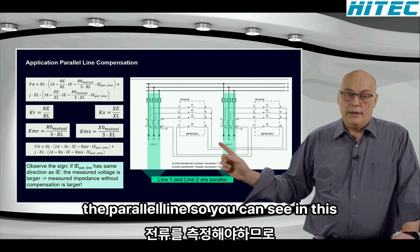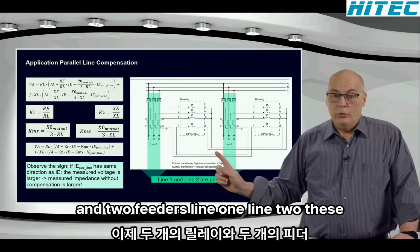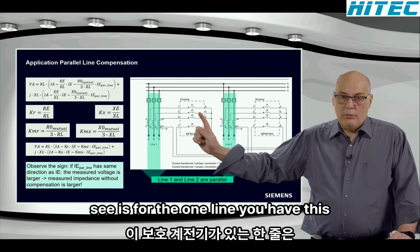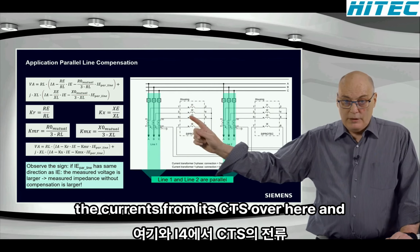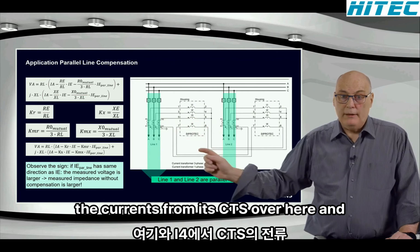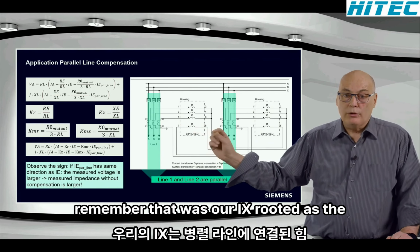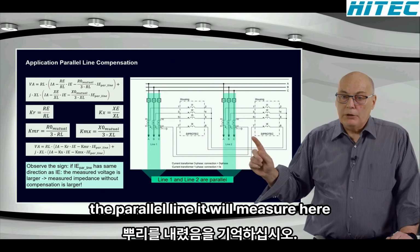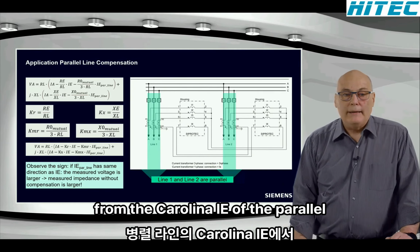So you can see in this diagram now we have two relays and two feeders, line 1, line 2. These are two parallel lines. And what you can see is for the one line, you have this protected relay. It's measuring the currents from its CTs over here. And at I4, as we did at the beginning, remember that was our IX routed as the forced current input. That is connected to the parallel line. It will measure here the residual current, the return current from the parallel line, the IE of the parallel line as such.